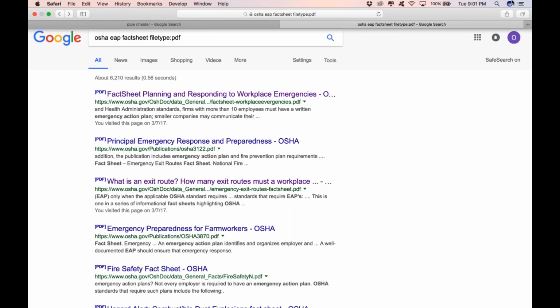And then one or more fire extinguishers not rated less than a 2A have to be provided on each floor of multi-story buildings. At least one fire extinguisher has to be located adjacent to the stairway as well. Okay, so it's going to have a designated fire extinguisher at a stairway, and it's going to be in the path to exit. So if we're in a basement and we have to travel up to get out, the fire extinguisher would be down at the bottom. If we're on a second floor and we have to travel down to get out to the first floor, then it would be up on the second floor. Okay, so it's always in the path to travel to get us to the exit.